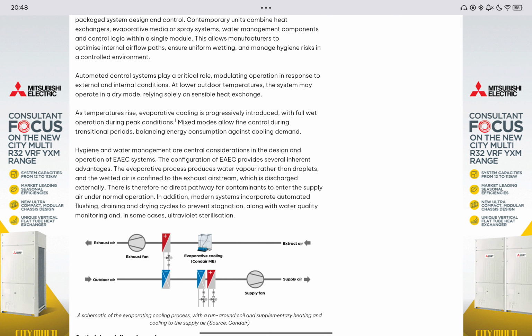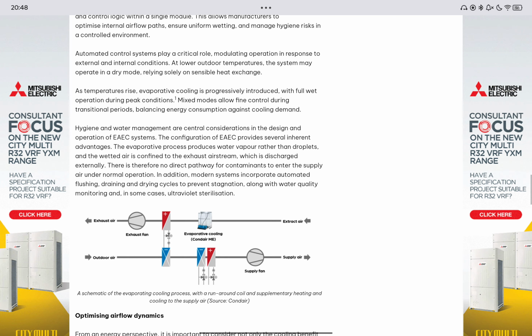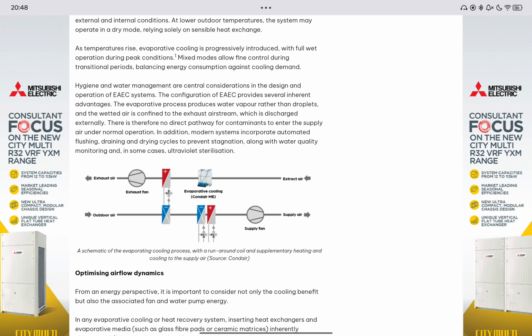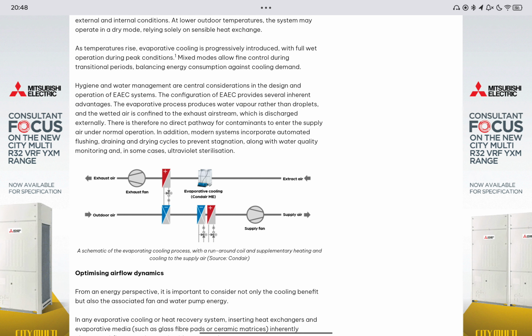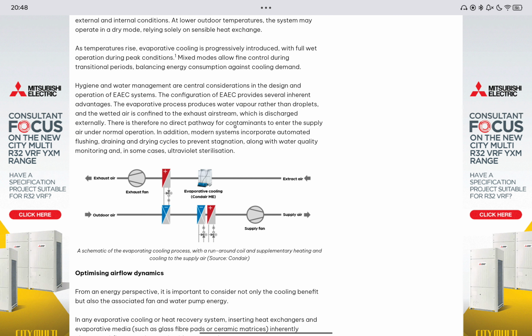At lower outdoor temperatures, the system may operate in a dry mode, relying solely on sensible heat exchange. As temperatures rise, evaporative cooling is progressively introduced, with full wet operation during peak conditions. Mixed modes allow fine control during transitional periods, balancing energy consumption against cooling demand. Hygiene and water management are central considerations in the design and operation of EAEC systems. The configuration of EAEC provides several inherent advantages.